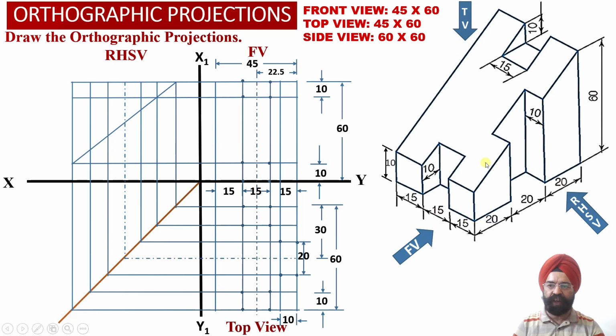This is the inclined surface. Now, wherever this surface and the inclined surface intersect, from this point of intersection we need to draw a horizontal projector line into the right hand side view orthographic projections, and we have to extend this horizontal projector line into the front view orthographic projections over here.